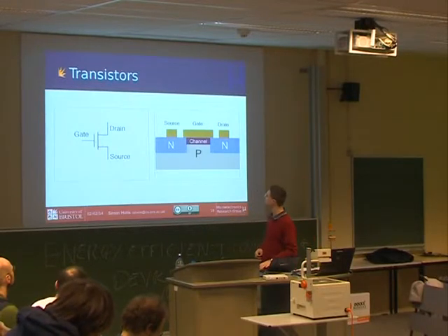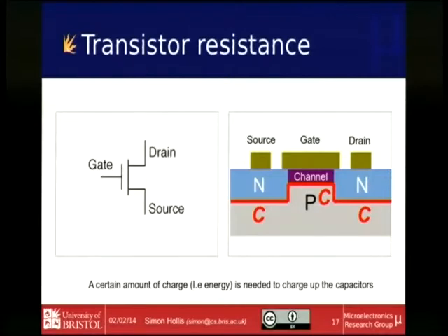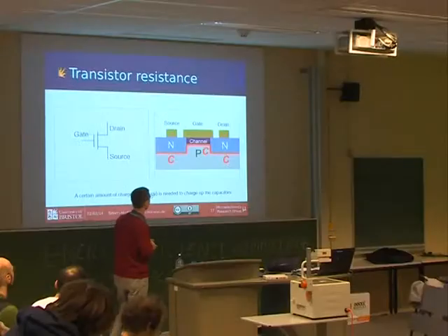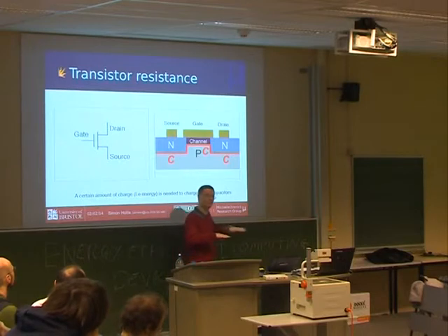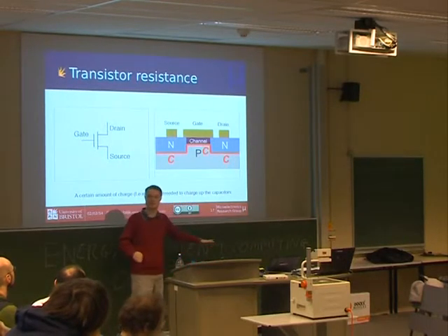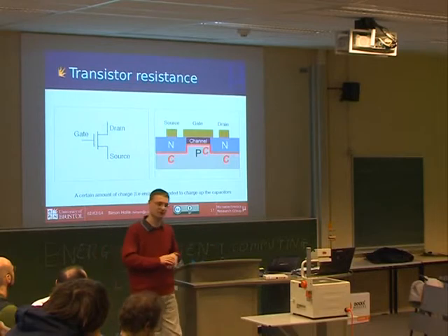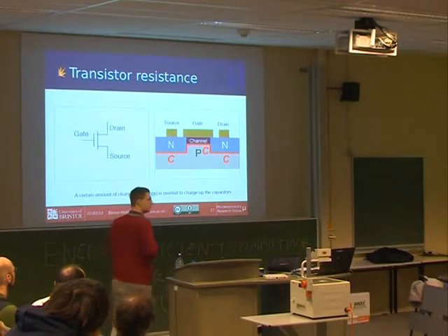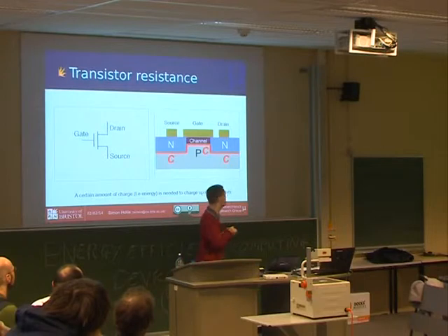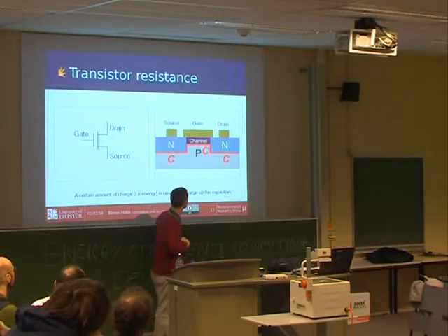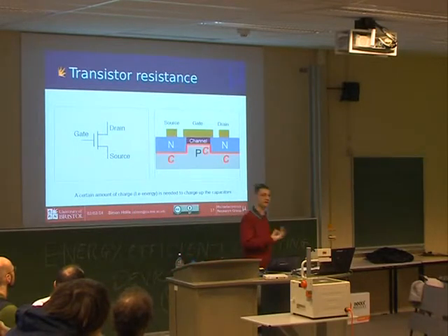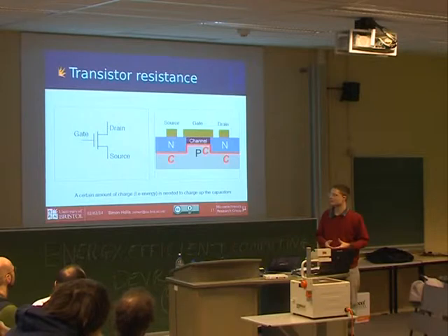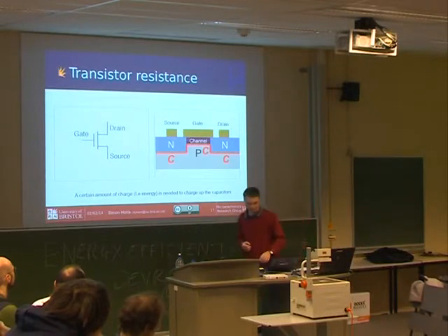Why? Well, the first thing is, if we think of one point of view, the two materials are separated together in the array. So, well, I've built a capacitor. This is a lovely parallel structure. That's how our industry has done so well, making these big, mass-produced, very flat devices. So I've got a big parallel structure, so what I've built myself is a parallel plate capacitor. And it's about as long as a transistor. So if I change the voltages at any point in the circuit, I actually start charging and discharging the capacitance system. That's that part of the circuit. So that means that I have to do some work.